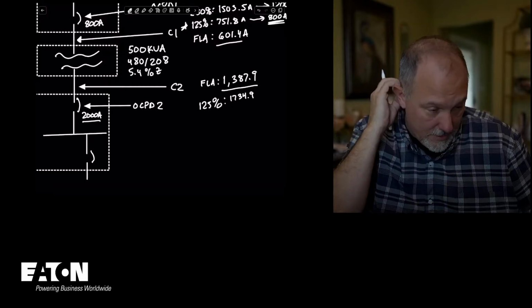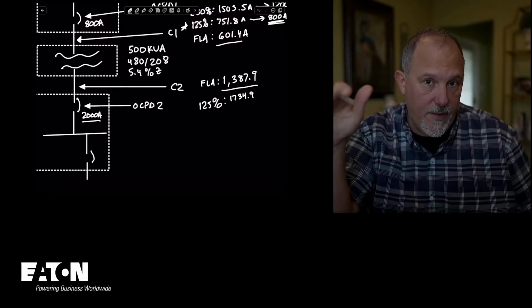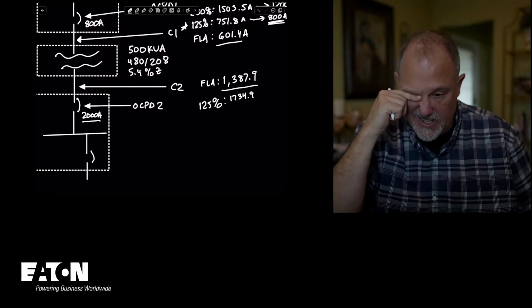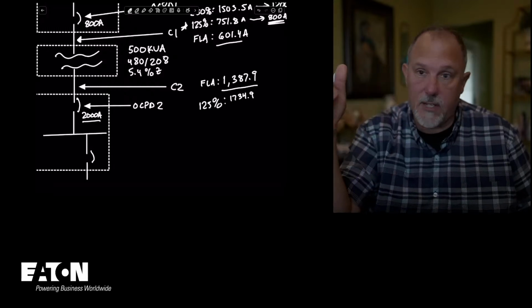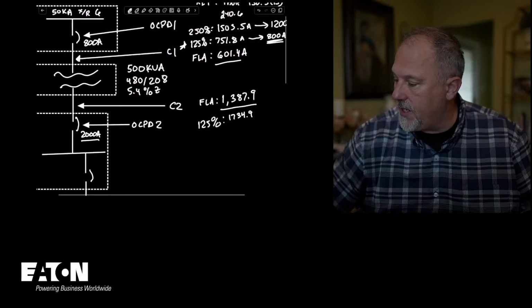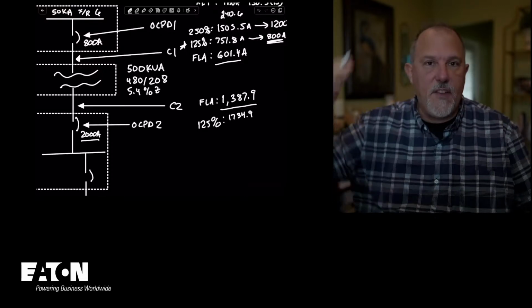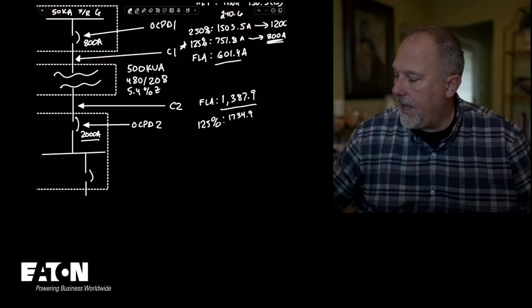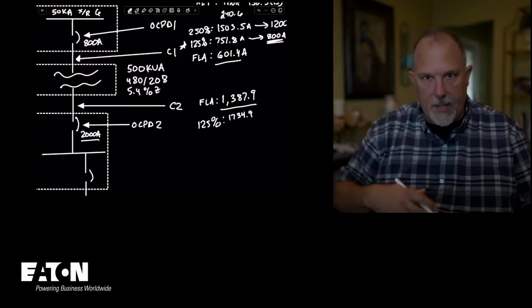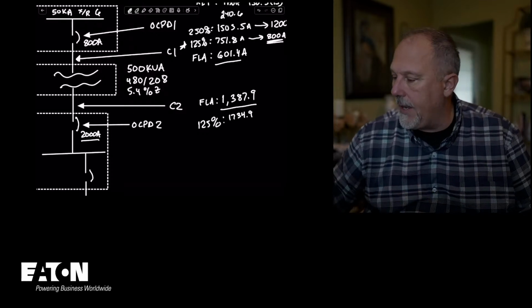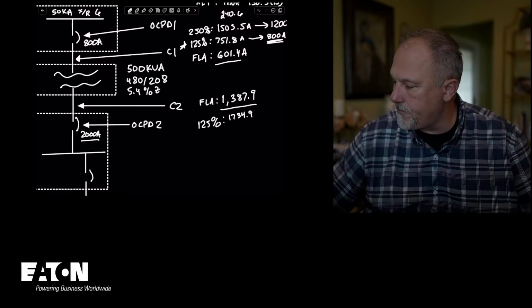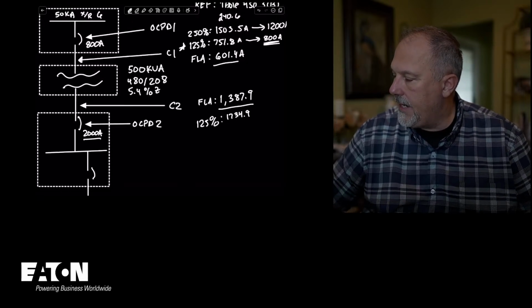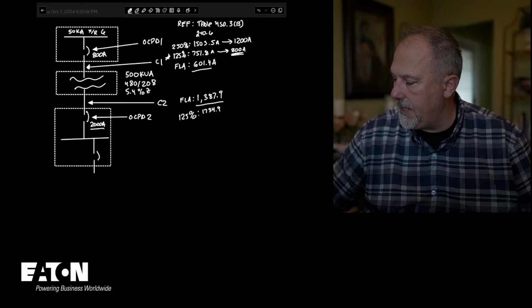All right. Remember, panel boards, I can go up to 2,500 amps on a panel board, but I'm going to use 2,000 amp. So I have a 500 kVA transformer, 800 amp feeder breaker. I have a 2,000 amp panel board that it's supplying, and now I want to pick my conductors. So my conductor 1.